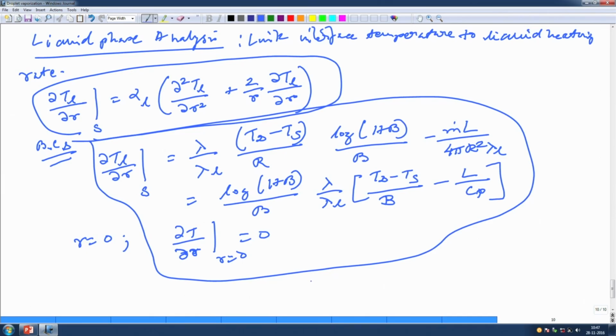And the initial temperature of the droplet, you can say the initial temperature was uniform, T equal to T naught. So the time derivative is considered in the liquid phase but not in the gas phase, and that is because, as we have already established, the gas phase does not require it because it is fast.